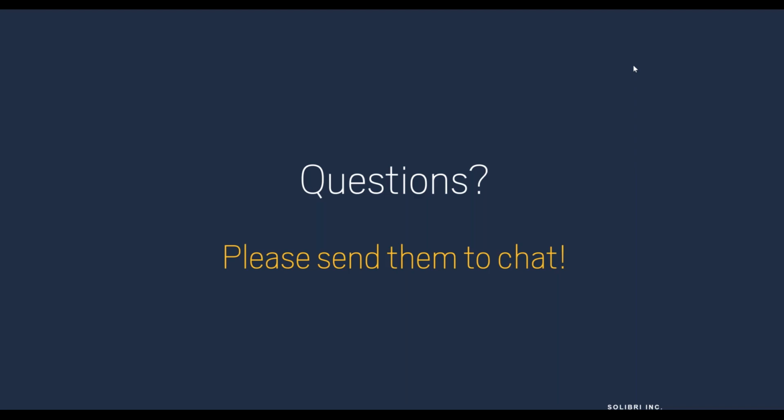I think that's a really good answer, because that picks up one of the next questions. I'm not answering questions directly, I'm trying to put them into a theme, and the theme is: are there any common issues with dealing with IFC? From our perspective at Solibri, when you're first setting up a project and starting to work with new partners, communication is vital. You need to discuss what IFC format you're going to support and what content you're going to put into the model, not just the geometry but also the property sets and whatever other data is associated with it. We do get issues where models come in and somebody's modelled at sea level and somebody else is modelled at real world level, and all sorts of things like that. So from our point of view, communication is the key thing there.